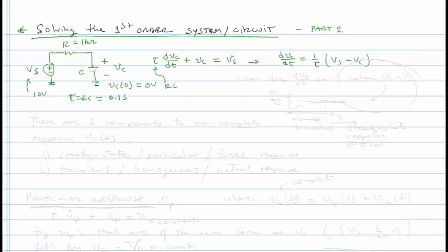So at time 0, when this first starts out, the voltage across the capacitor will start rising at 100 volts per second. Not long after the voltage starts rising on the capacitor, you no longer have all 10 volts of Vs across the resistor, right? You have Vs minus Vc, so you have a little less than 10 volts. And what that will do is result in slightly less current going in and charging the capacitor. And as this progresses, there will be a decreasing rate of charging as the capacitor voltage goes up.